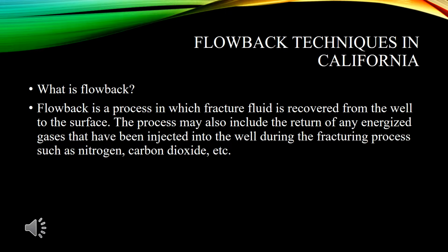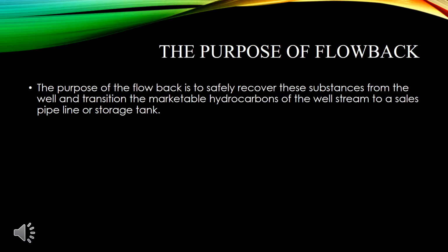The process may include the return of any energized gases that have been injected into the well during the fracturing process, such as nitrogen, carbon dioxide, etc. The purpose of flowback is to safely recover these substances from the well and transition the marketable hydrocarbons of the well stream to a sales pipeline or storage tank.